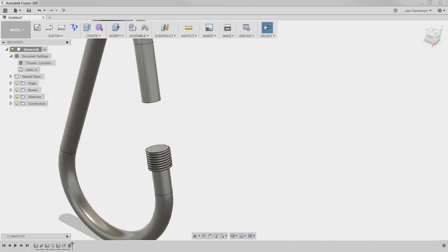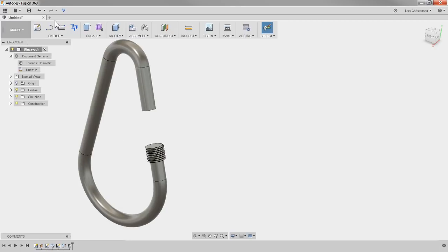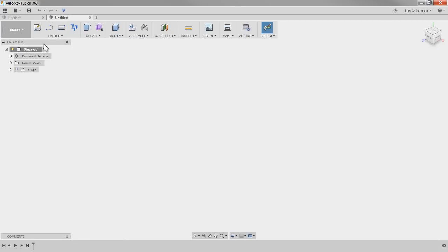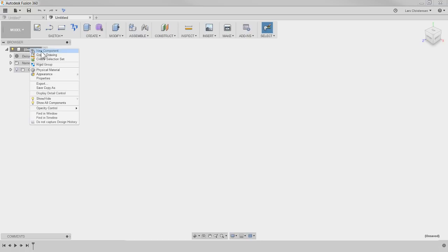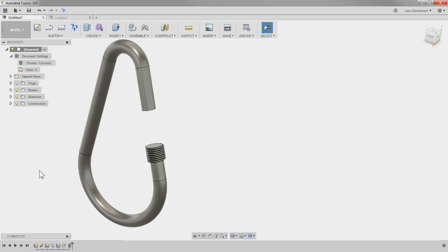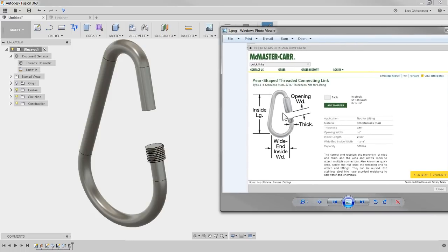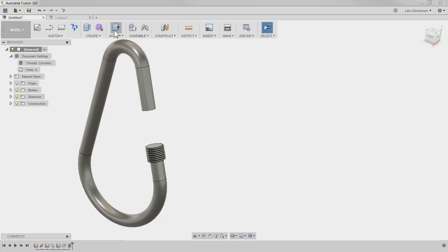And that goes into, and I'm going to probably do a live stream about this at some point. There's something called rule number 1 on the forum, that anytime you're starting a brand new model, you should always start out by right-clicking and say create new component before you sketch anything. Because then you will never run into what is happening next. Right now, this is just one component, right? But then when I draw the key, the little locking mechanism here, well, there's another component.